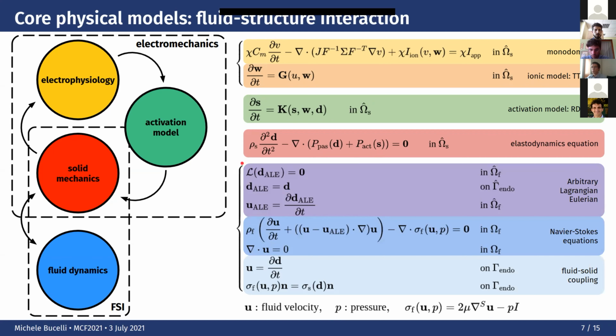Now we operate in the ALE framework, so we have fluid dynamics in a moving domain, and the first three equations in our fluid dynamics block, let's say, are concerned with the extension of the solid displacement from the fluid-structure interface to the whole fluid domain. We do so by means of an arbitrary linear operator. We typically rely on linear elastic lifting for this purpose, since we have found linear elasticity to be robust enough for our simulations.